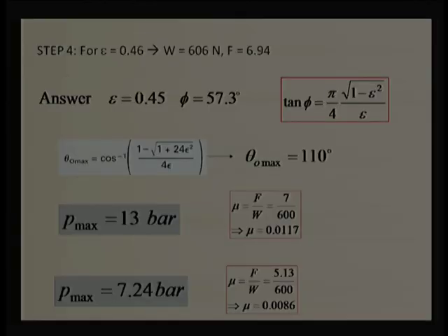That is what we gain from studying lubrication mechanisms and understanding tribology. Otherwise, if somebody says the load carrying capacity is okay, we will go ahead with the maximum length. That is wrong. Here, the smaller length gives more benefits: lesser maximum pressure, lesser coefficient of friction, lesser space, lesser cost. That is essential for us, and obviously that is going to give us overall economics.